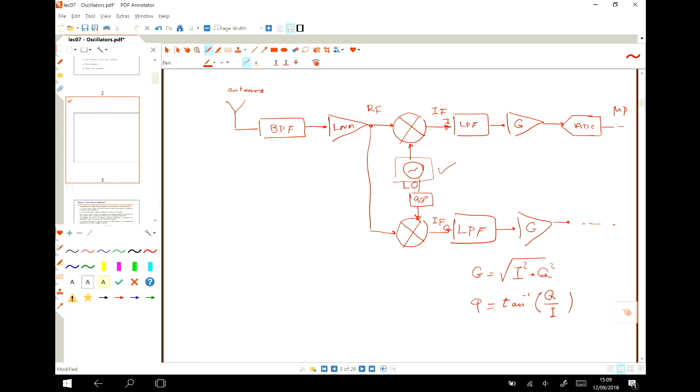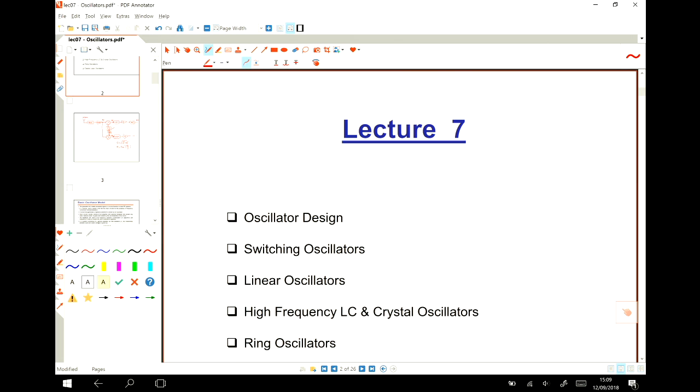The same thing in the transmitter. So again, we need this component to up-convert our signal and then transmit it. So no difference. Just assume that the signal is passing this way. So you have a D2A and a filter, amplifier, and then up-convert the signal, amplify it, and then send it through the antenna. Okay?